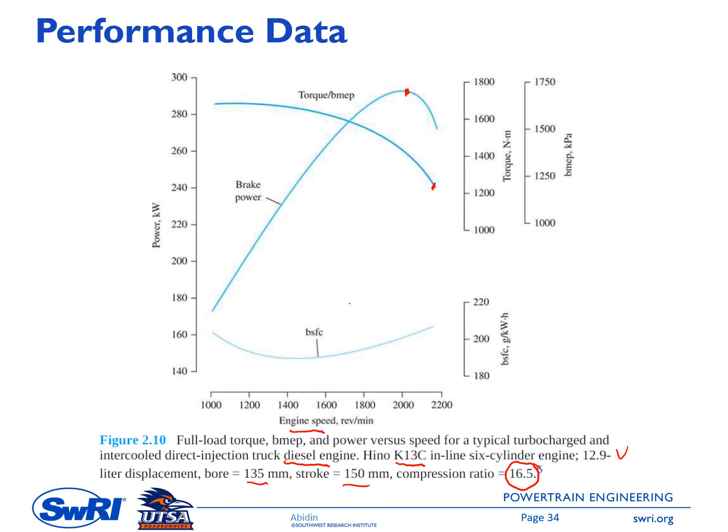So depending on the relative size of the turbocharger to the engine, the turbocharger might be able to increase the torque at low engine speed. So this is actually when we use a small size turbocharger. If we use a larger turbocharger size, then we might have something like this one. So this is just an example. Okay, so you might have something like this one.